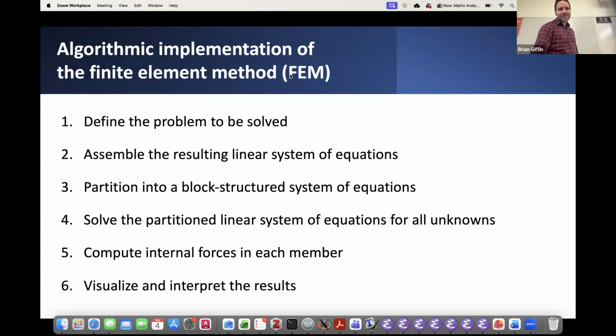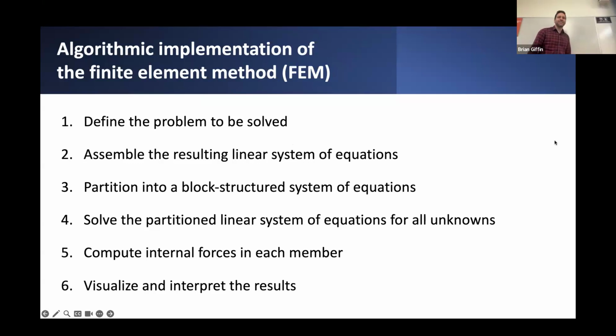And the intention is really to demonstrate that the methods are pretty much the same in terms of how you would go about solving these problems and implementing a finite element method. A lot of the steps are the same. There are only a few minor modifications that differ from what you're used to seeing in the one-dimensional finite element context. So we'll step through and show where those differences arise, but otherwise it's essentially the same sequence of steps that you would follow. It's a very similar looking MATLAB-based program if you were to implement this. And the intention is to show that the methodology is very generic and can be extended to accommodate these multidimensional problems as a generalization.